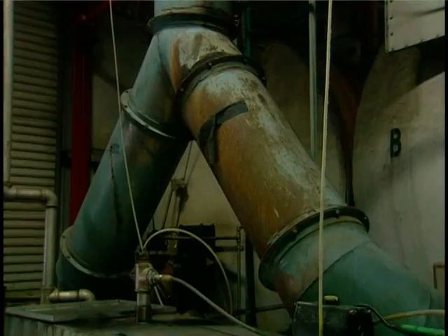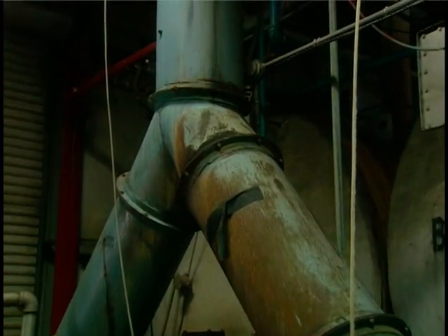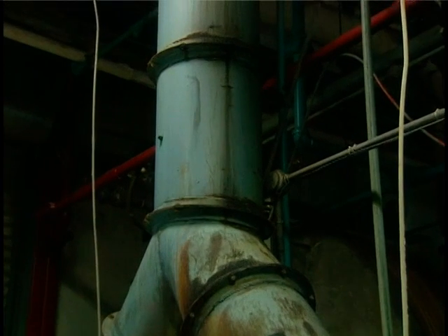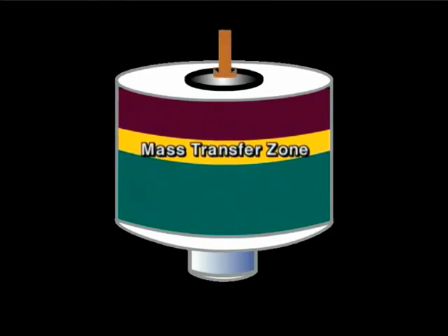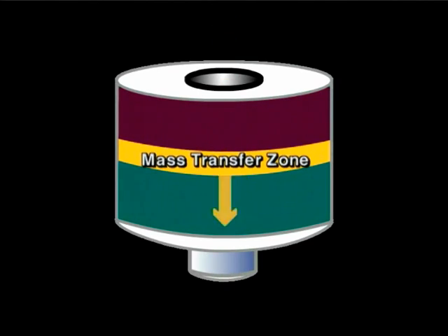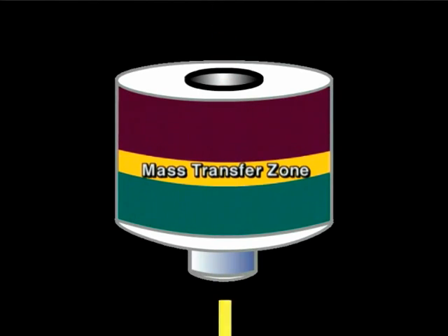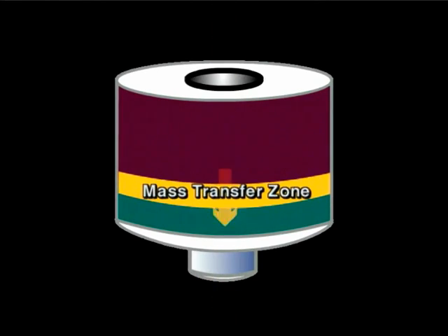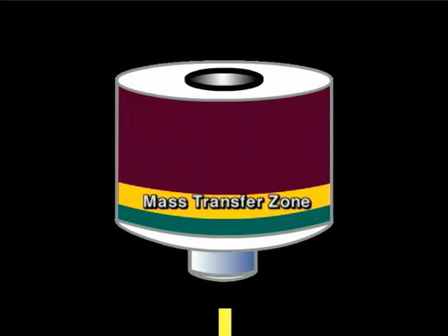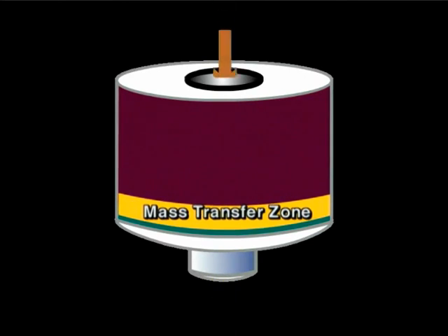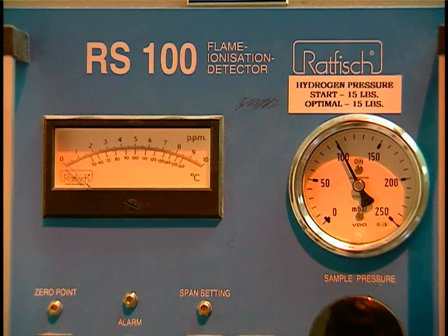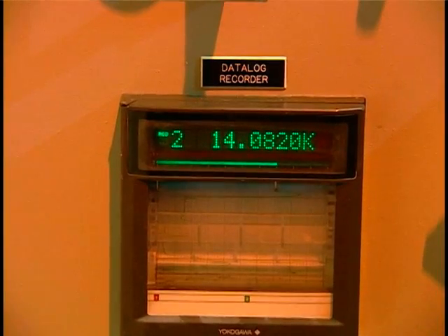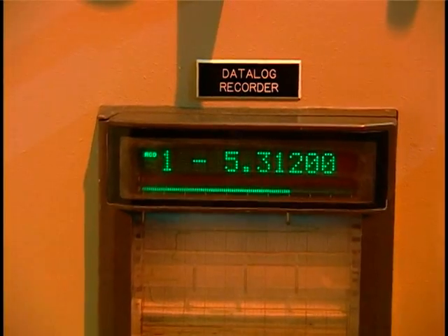The most direct measure of the performance of an activated carbon adsorber is the organic vapor concentration in the outlet gas stream. Active adsorption occurs in a thin mass transfer zone that moves down through the carbon bed until the breakthrough point is reached. If breakthrough is occurring, the outlet concentration from each bed will be highest just before it's regenerated. If there is a permanently installed analyzer, the adequacy of the data should be checked as part of the overall performance evaluation.